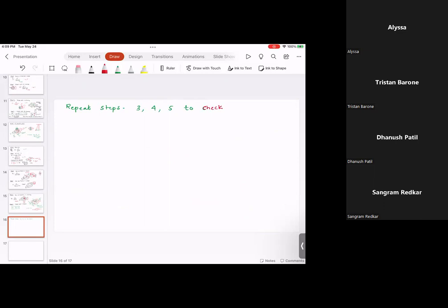Checking the forked end in tension: sigma is equal to P divided by (D2 minus D1) multiplied by 2 times T. And this should be less than sigma T.